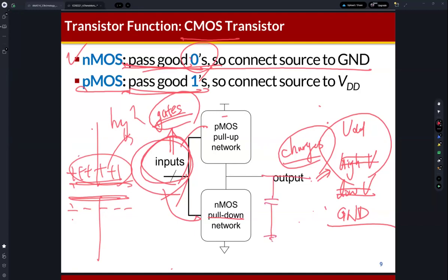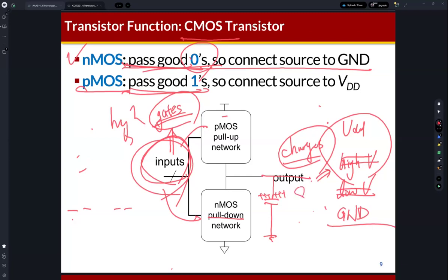There is a capacitor here. Actually this is not a real capacitor, it's a parasitic capacitor. But if we store positive charges in this capacitor, at this plane, then we can make the output voltage high. Then how? You can find the VDD is here. Another node of the PMOS transistor is connected to the VDD, and the input is connected to the gate of the PMOS transistor. So this VDD is connected to the output node, and then we can store positive charge in this capacitor, right?